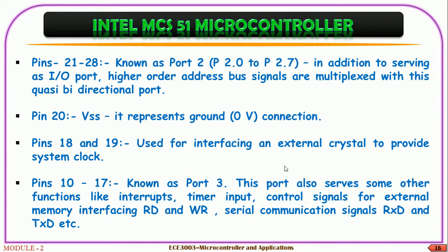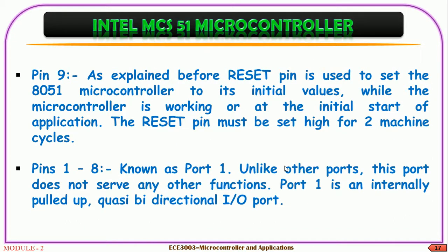Pin number 9 is reset. While the microcontroller is working, or at the initial start of the application, the reset pin must be set high for 2 machine cycles. Pins 1 to 8 are known as port 1.